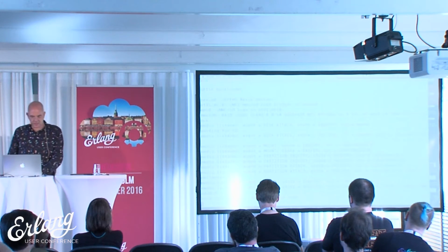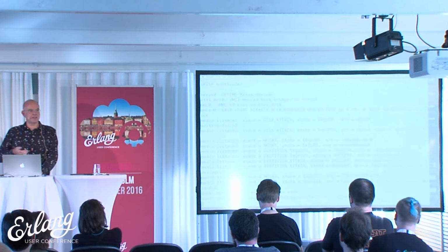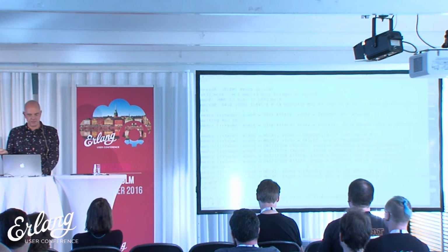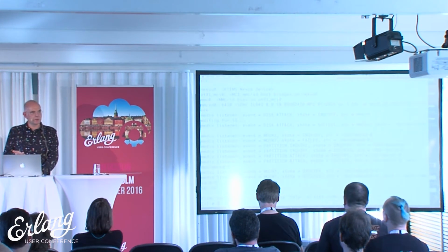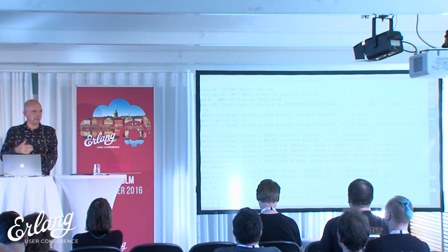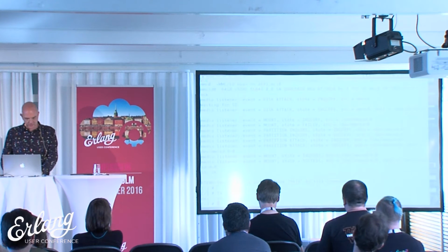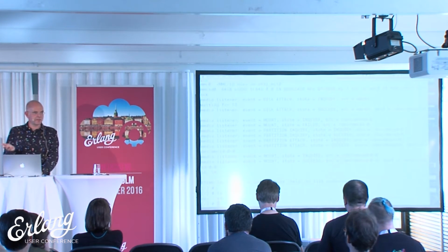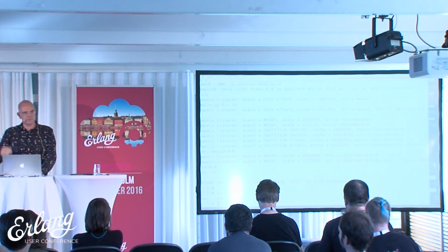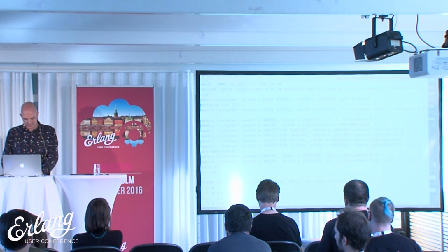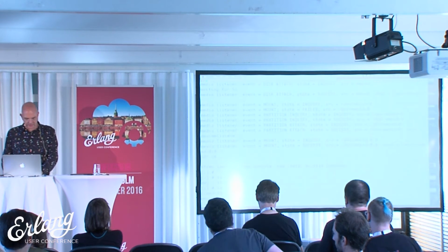So there we have it. This is a demo which also has an SD card driver in the application, so I should be able to look at the SD card contents from the RTEMS shell. So let's see, I do an ls. There's dev, and etc is in the RAM disk, and media is where it mounts stuff. So let's go to media. It's a very limited shell, so you can't do autocomplete or anything.